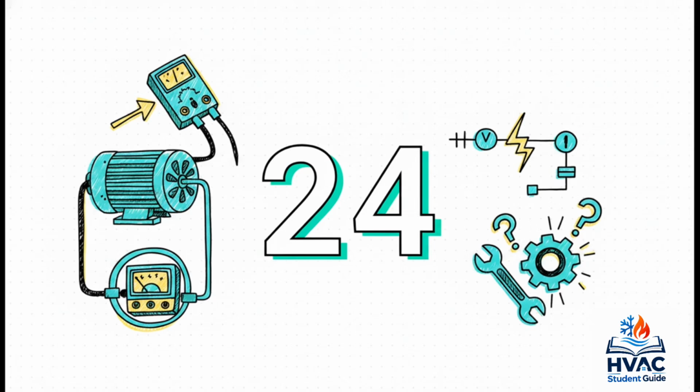Let's apply that textbook math to the real world. Say you're standing in front of a 240-volt motor circuit, and your clamp meter shows it's drawing exactly 10 amps. What's the impedance? 240 divided by 10 gives you exactly 24 ohms of impedance. Running this quick calculation helps you instantly verify if the voltage, the current, and the circuit opposition actually make sense together, or if you've got a failing bearing or a mechanical bind somewhere.